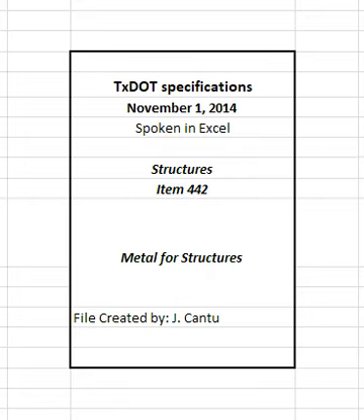2.1.3.1 Miscellaneous bridge components. Provide steel that meets ASTM A36, A709 grade 36, or A500 grade B for members such as steel bearing components not bid under other items, steel diaphragms for use with concrete bridges, and armor and finger joints, unless otherwise shown on the plans.